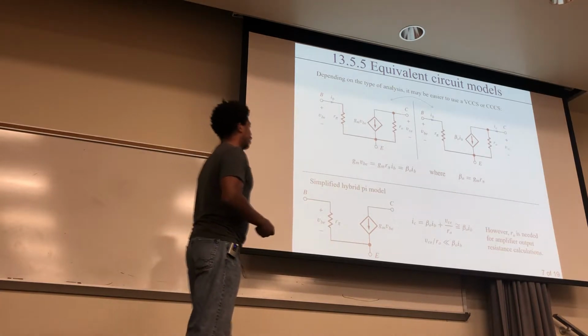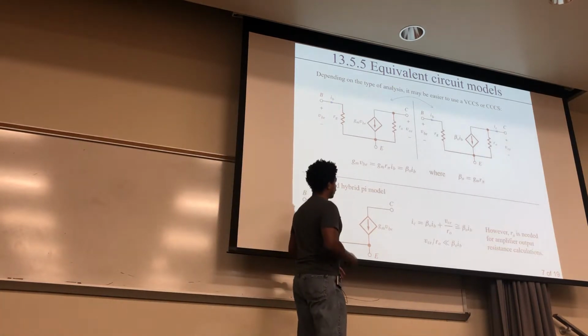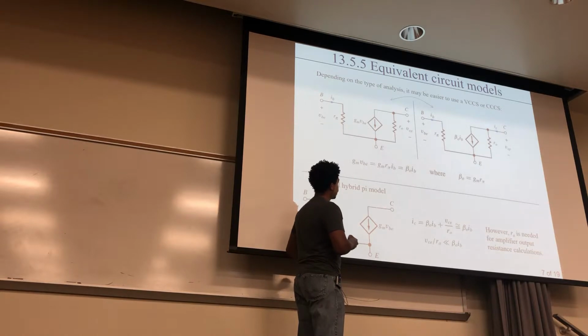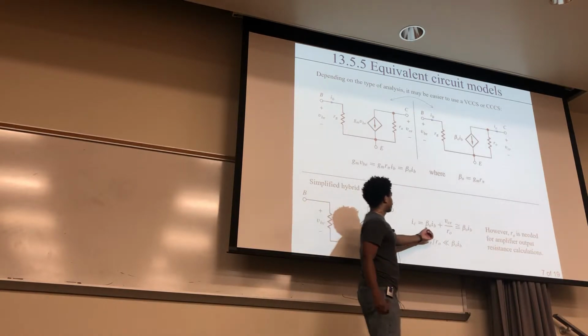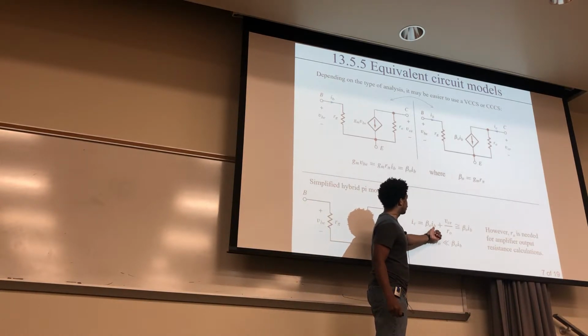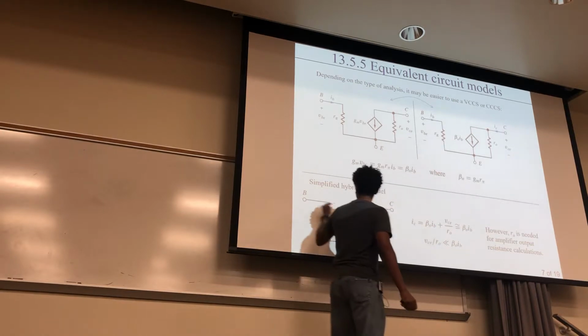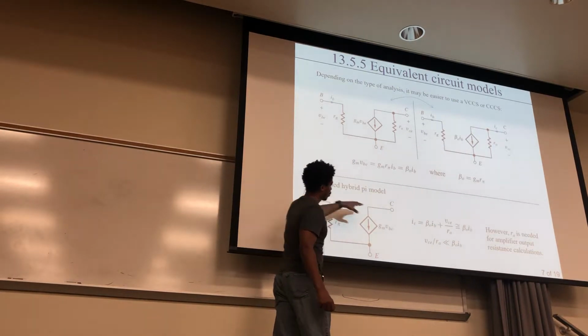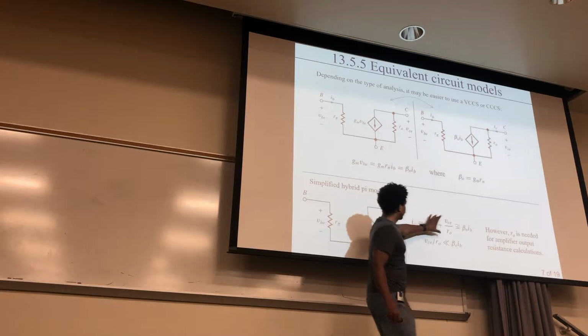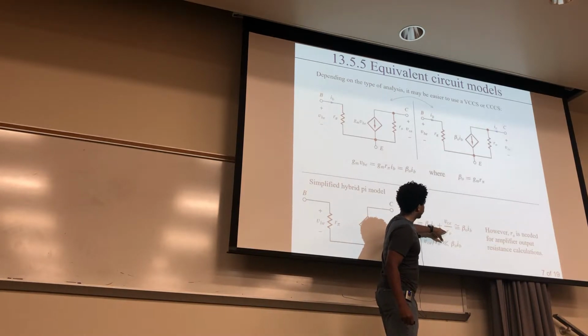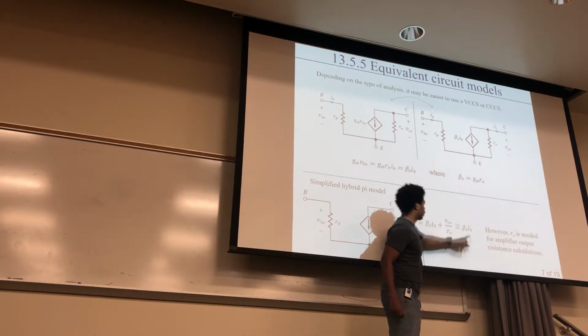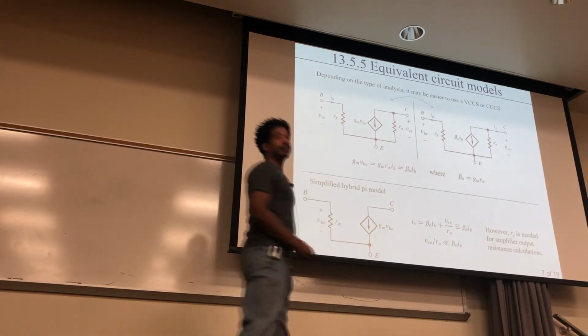Okay. So in that case, this current IC right here is just beta times the input current I right here, so it's proportional to that. This right here, if that's really large, that's small, this component can often be neglected, and so it just equals that right there. Okay.